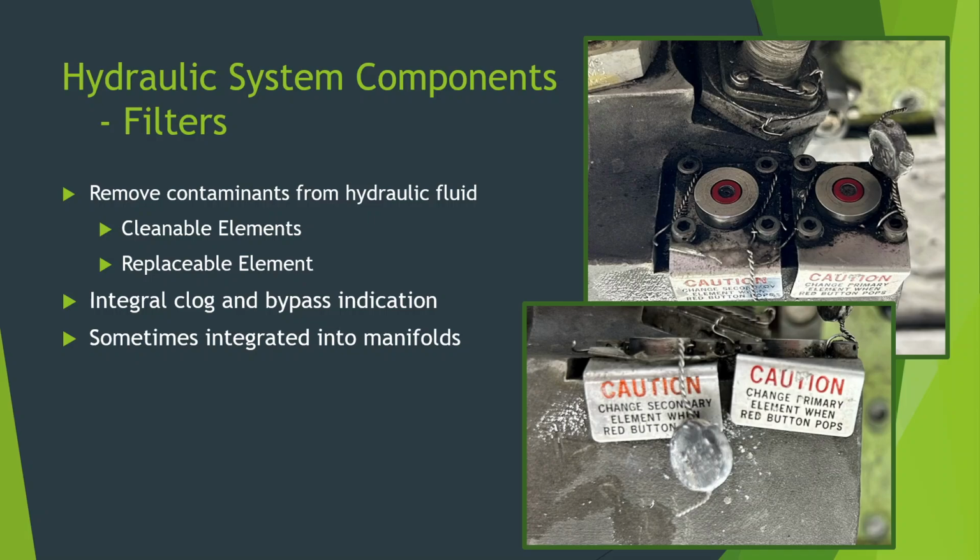In some cases, these bypasses can have a pressure sensor or a switch attached to them if you want to give some kind of an indication up in the flight deck. Not all of them have it, most of them actually don't, but if it's one that's particularly important, they may link it to an indication system. If you see that cannon plug above, I misspoke, they do have a pressure indicator right above, but it's not integral with the bypass indicators. It's a separate little switch above. That's what this threaded cannon plug goes to right here. It's separate, but it does the same thing.